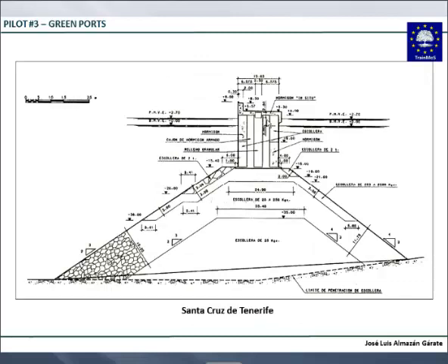This is one of the deepest vertical dikes in the world, because this is just the base of the dike. The limit of the energy is around here, so all this part is not affected by wave energy. So this is just leveling or raising the bottom of the sea. This is the dike structure, and this is a full dike structure. But look at the depth here. This is 15 meters of depth, because it's 3 meters plus 13 meters, more than 16 meters of depth. And this is 54 meters of depth.